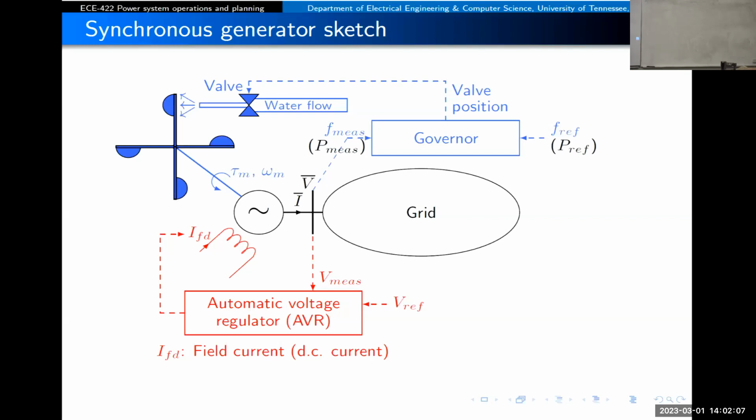But you also have one generator that defines the slack bus. That generator has a constant voltage and constant angle, with the assumption that that bus in the system will maintain the frequency at the synchronous, nominal frequency. And that's the slack bus. We can assume that it is a very large generator with a large capacity that can keep up with whatever power we need to generate to keep the frequency at the nominal value. In that case, we will use the frequency to adjust the generated power to keep the frequency at the nominal value.